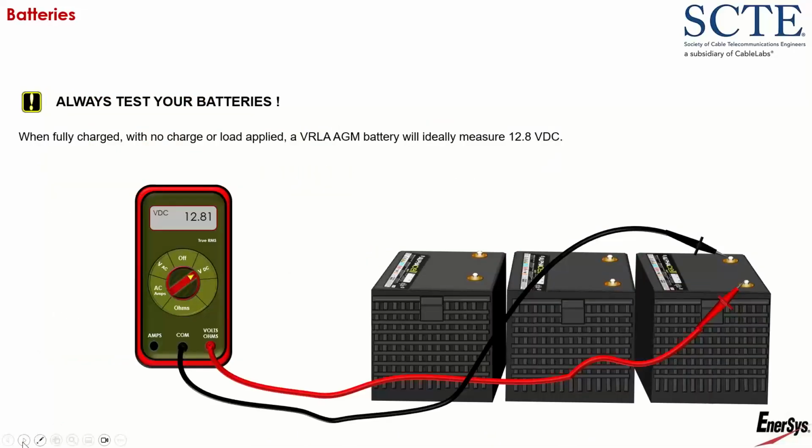Always test your batteries. I get calls from technicians all over the country. The reason I'm stressing this, I just got a call from a technician a couple days ago, and when I asked him what the voltage was on his batteries, he told me, George, I just got them out of the warehouse. That doesn't mean they're good. And in his case, they weren't. So always test your batteries.